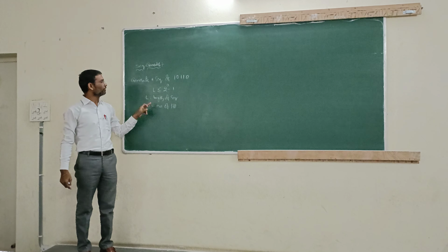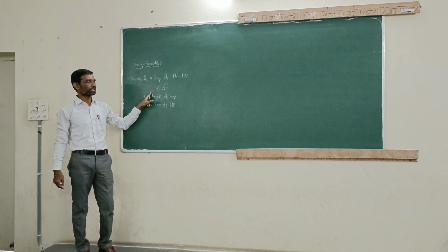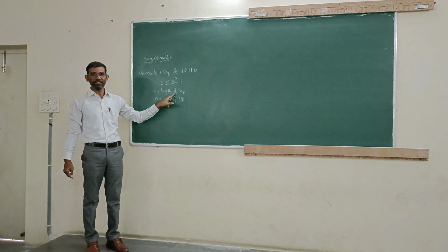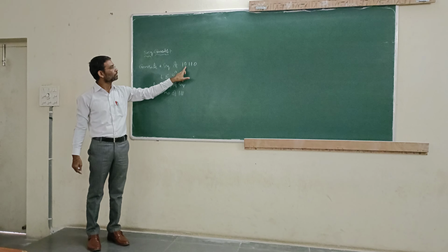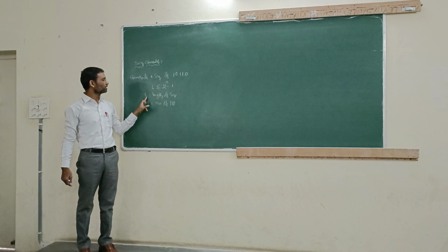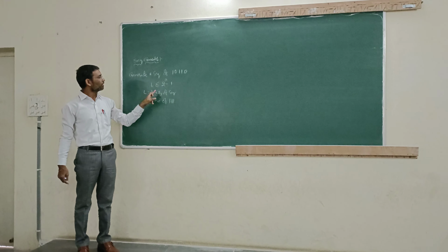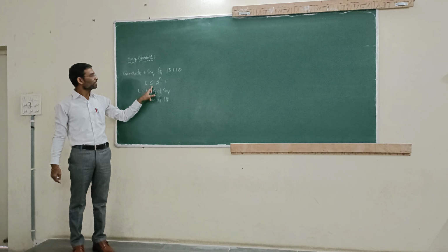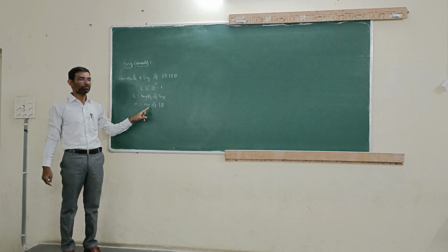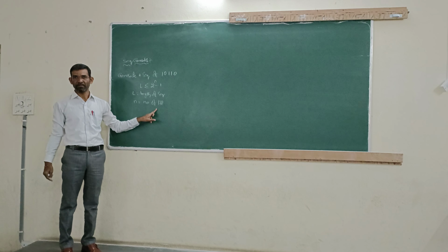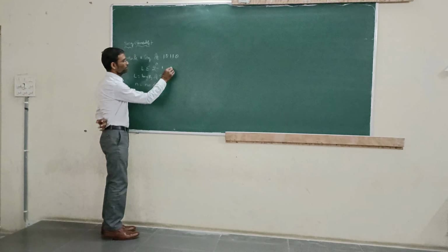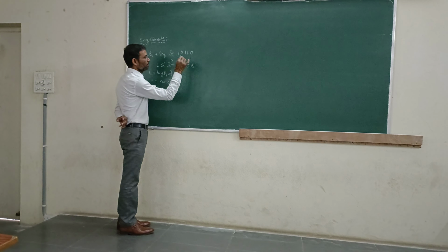So here we are using a simple condition, where capital L is nothing but the length of the sequence. Here we have 1, 2, 3, 4, 5 bits in our sequence, so capital L is 5. L is less than or equal to 2 to the power of n minus 1, where small n represents the number of flip flops. So here L is equal to 5, so 5 is less than or equal to